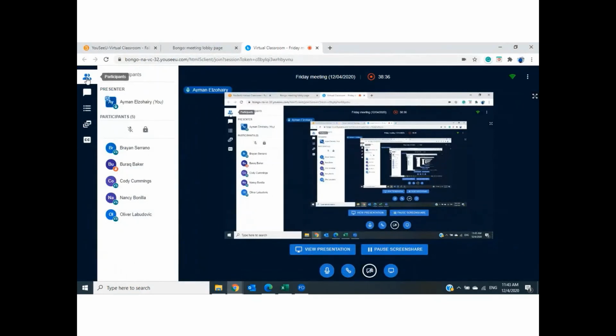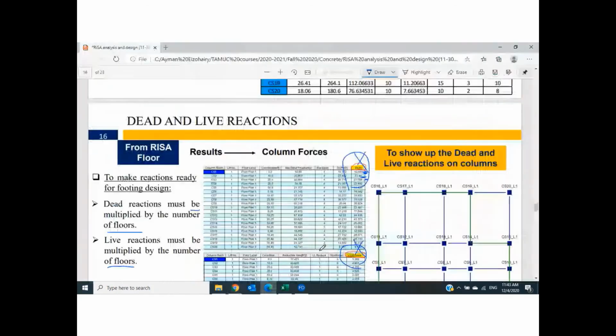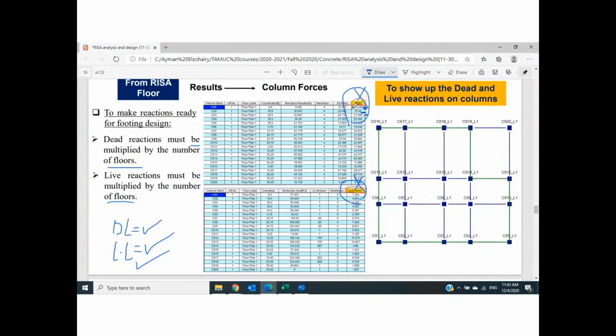Any other question? Dr. Amy? On the term project one, where it says 10 floors, you said you were going to show us later how to do 10 floors on RisaFoundation. Can we do it on RisaFoundation? No. RisaFoundation, I did already. Do you remember when I multiplied the reaction dead load by number of floors? Oh, from last time. Yeah. Just calculations. We don't need to define. Just calculations. Your reaction from Risa floor, multiply it by 10 before applying this load to RisaFoundation.